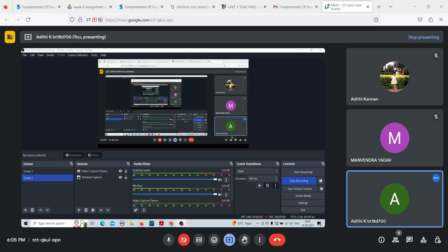That is also equal to 401.92 millimeter square. From there, if we calculate the diameter, we get 401.92 divided by pi, and you take a root of it, you get the diameter, which is 11.31 millimeters. The answer is option D. Any doubts in this?